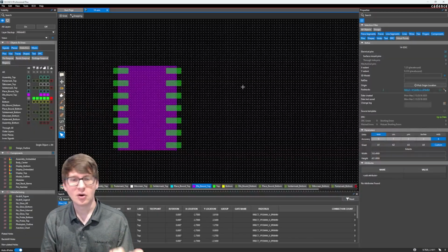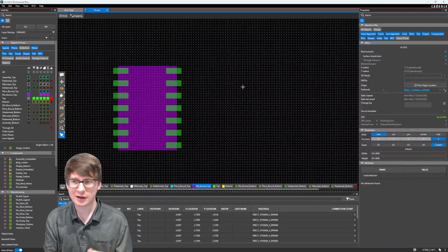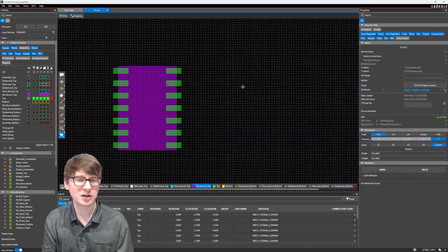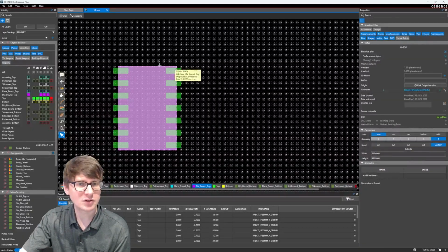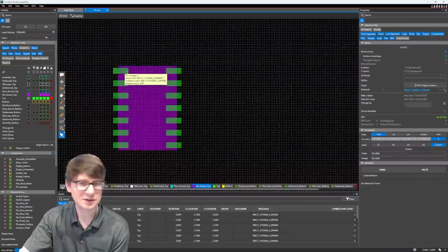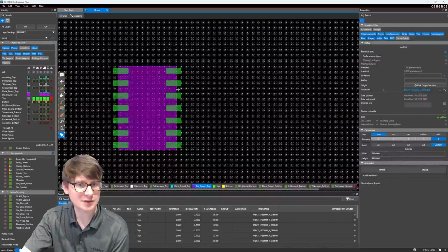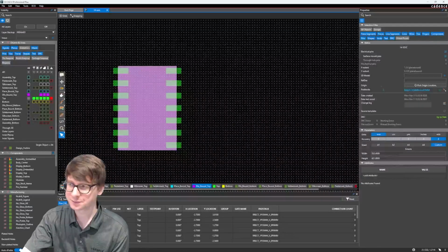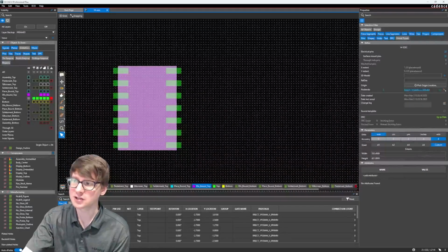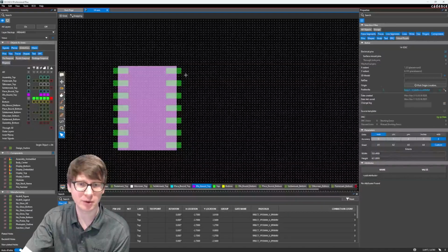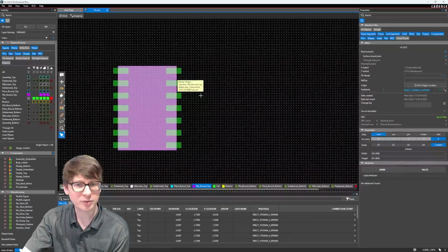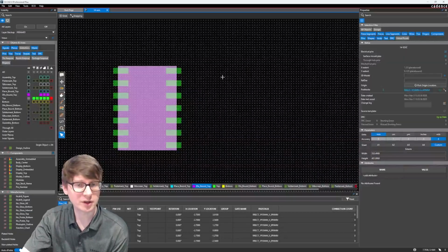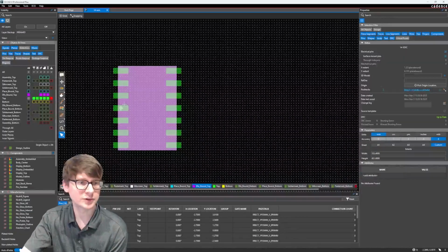Now, specifically for assembly, when you're assembling with a manufacturer, they will specify a restriction, for example, that no components can be any closer than 3 millimeters away from each other. Now, when you're measuring those components, they're talking about the physical component that's placed on the pads, not the actual copper pads, but the component itself. So what we've done is we've outlined the shape of the component, including the pins, and then that component will be measured against the outline of another component to see if we're meeting those DFA rules.